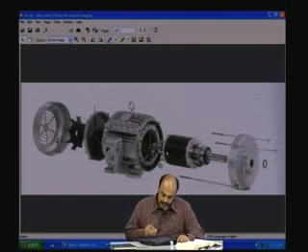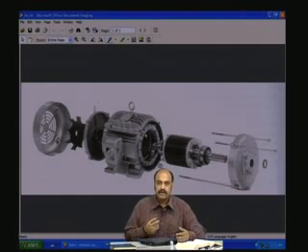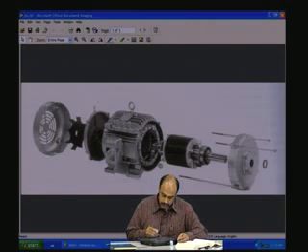So this is a rotor, and then inside here you see some coils or windings, and that is the stator windings which form the various poles, the A phase poles, the B phase poles, C phase poles, so on, which are wound on the circumference of this stationary system, and that is called the stator.